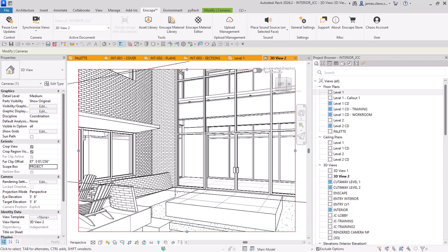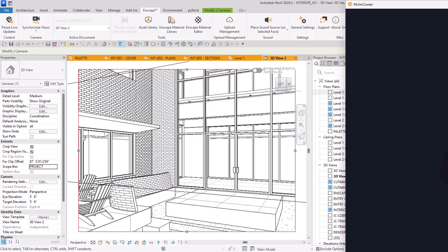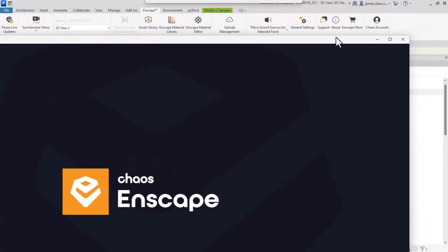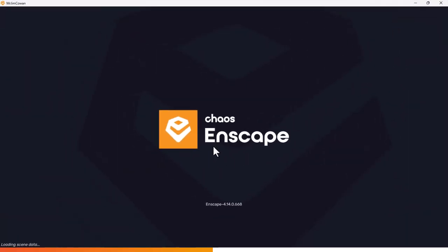This was updated yesterday, so this gets updated probably every 3 months. So what I did to verify the model, and the reason I added in my own model, I added some windows to borrow some light from adjacent rooms and things like that, was because I can see that the model is actually quite dark in certain areas, not enough natural light.